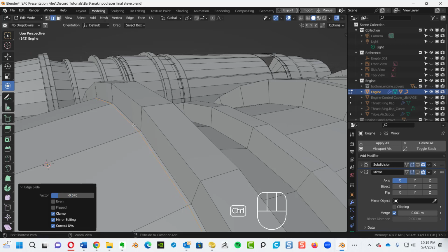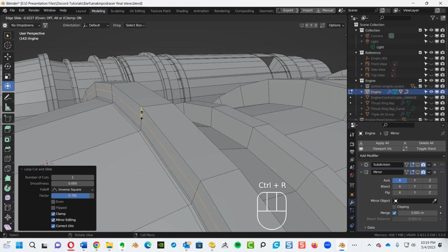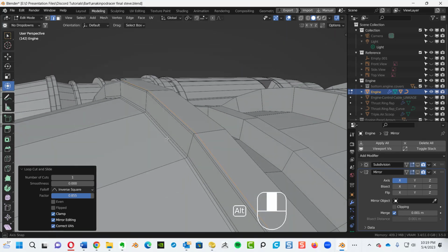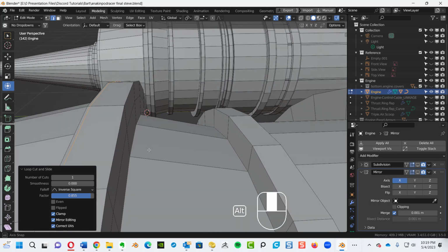All right, so Control R. Remember, it's going to be perpendicular to whatever edge that you put it to. So now that edge is held right there. Let's go to this edge. Command R. Hold the edge there. Okay. Command R. Hold the other side of the edge right there. So we're basically adding, it's like adding vice clamps to ensure that edge maintains its shape.